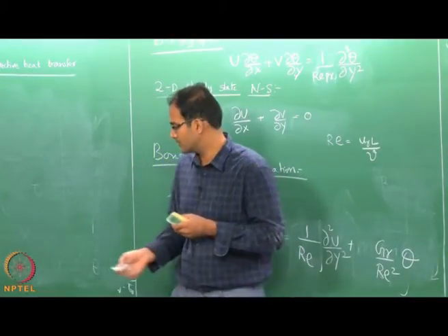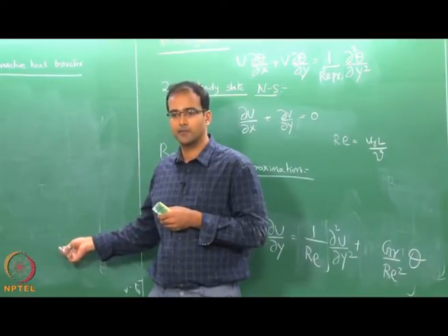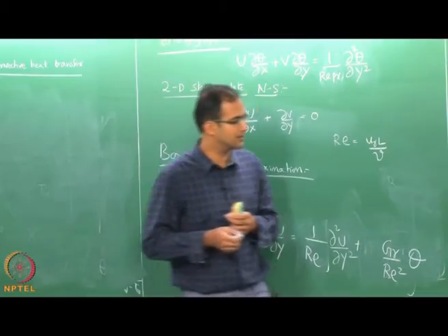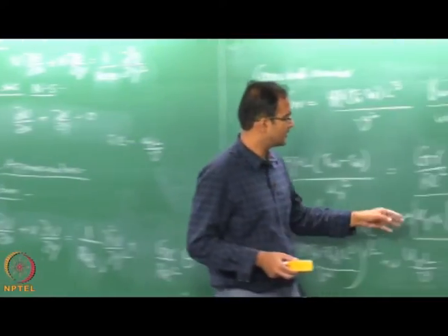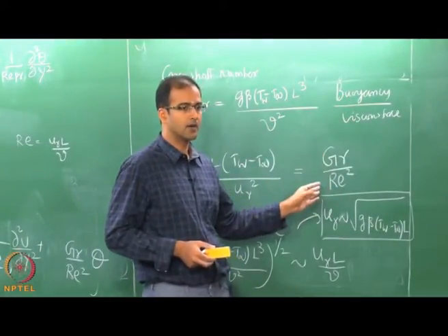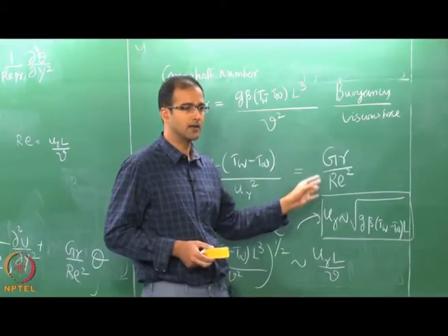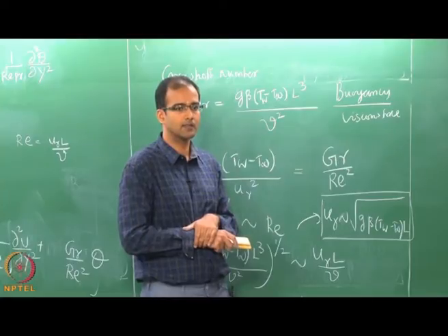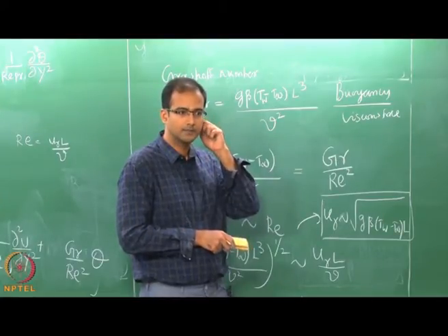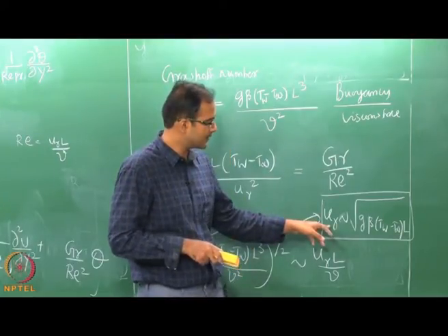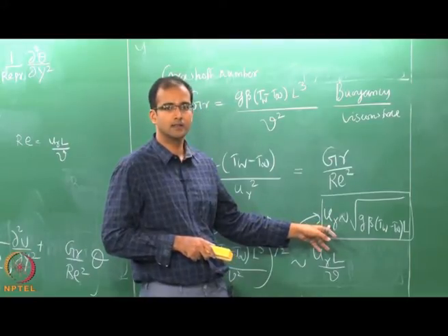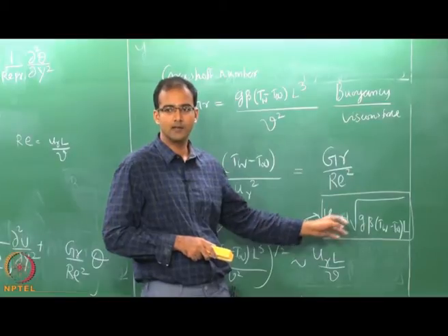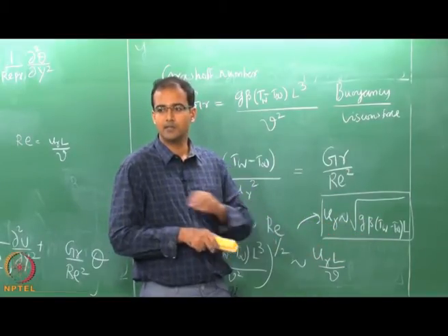Otherwise, when you non dimensionalize it, you do not know what is your reference velocity, but you can now, using the order of magnitude between Grashof and Re square, come to a reasonably good estimate of reference velocity. Okay. So, you can see that this reference velocity is nothing but what is going into your Reynolds number definition, and here it is driven by your temperature difference.